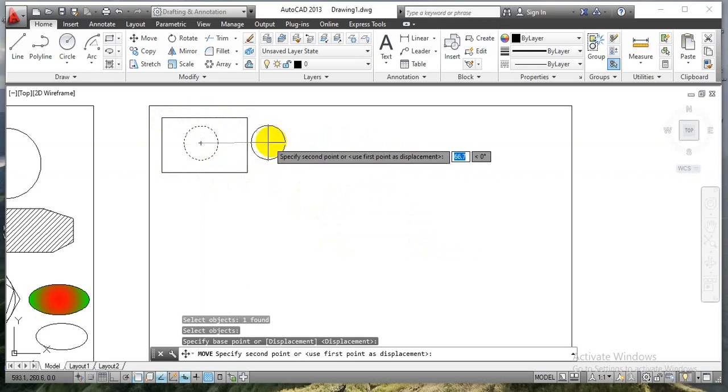Now if I just move my cursor, you can see I am able to move this circle with respect to that selected base point outside that rectangle. Okay. Otherwise, you can mention the distance over here as well. Now if we just look out the screen, okay, we have one rectangle highlighted by the blue color. In that the current dimensions are 73.1. So I can move that circle at a distance of 100 mm, okay, as per our requirement, and you can mention the inclinations as well.